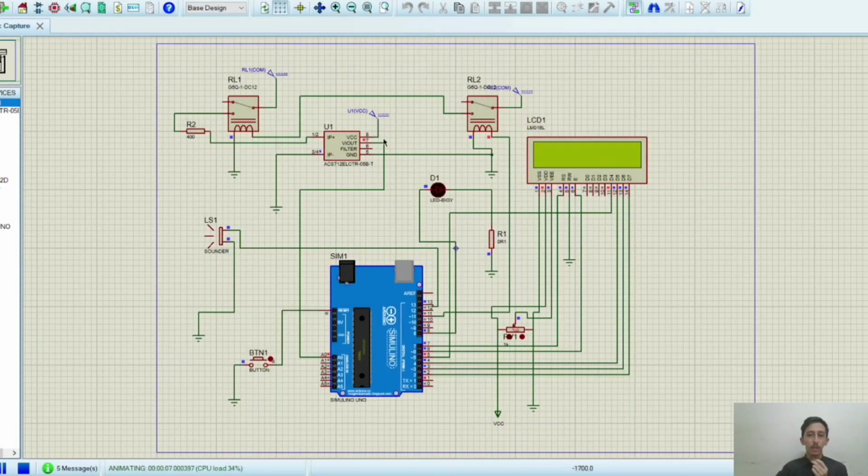Okay, as you know, the shown value is 0.03 ampere. I use Ohm's law, which is V over R, to get the value of current. The value of voltage that I put is 12 volt and the relay is 400 ohm, so it will divide and give 0.03 ampere.